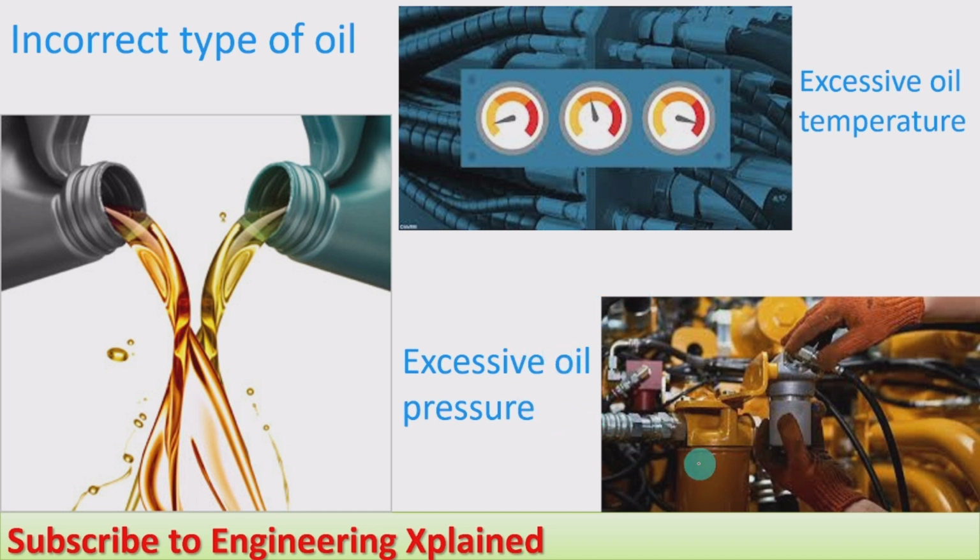The excessive oil pressure means in the system we pressurize the fluid by using the pump, and due to a blockage in the direction control valve or in some of the other devices like the pressure relief valve, or it may be the flow control valve, if any choking or any obstacle is there, the pressure within the system will increase. Also sometimes during the operation, wrong operation will also cause an increase in the pressure in the system. And there is the pressure relief valve.